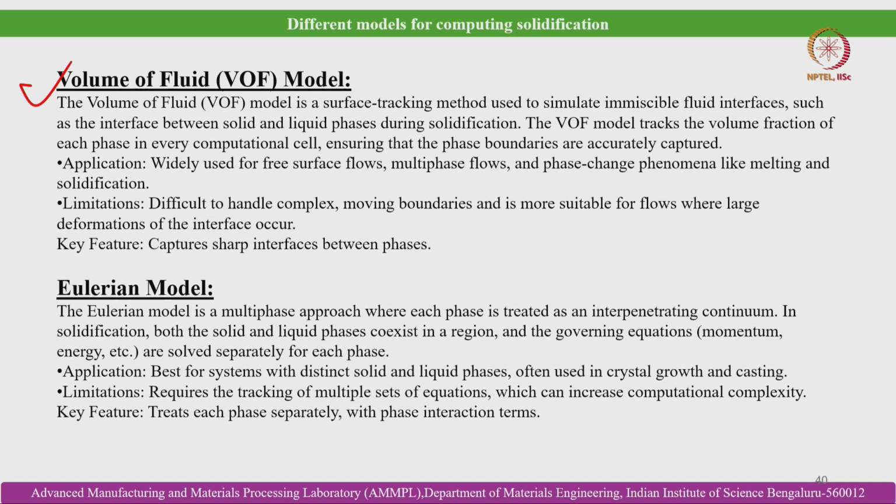What are the applications? It is widely used for free surface flows, multi-phase flows and phase change phenomena like melting and solidification. The limitations are that it is difficult to handle complex moving boundaries and it is more suitable for flows where large deformations of the interface occur. And the key feature is that it captures sharp interfaces between phases. These are the minute points about the volume of fluid model.